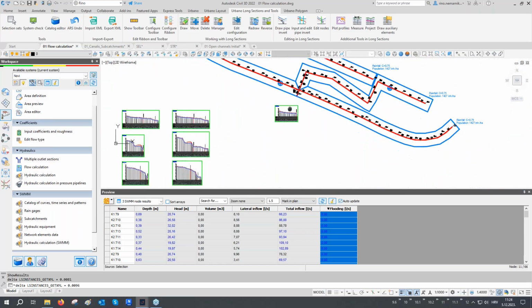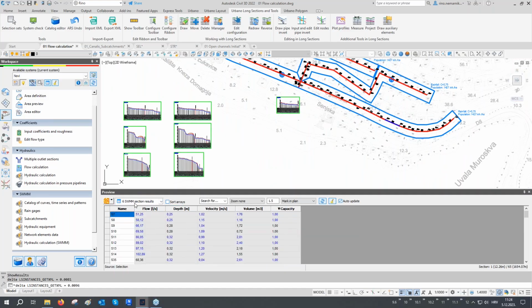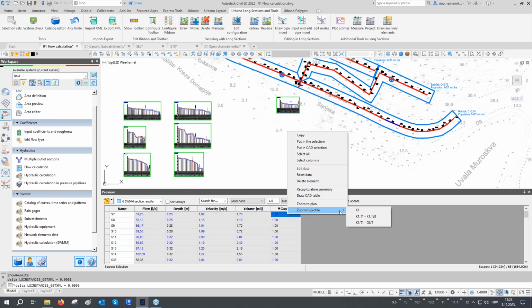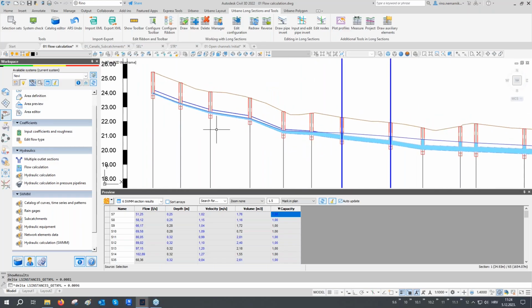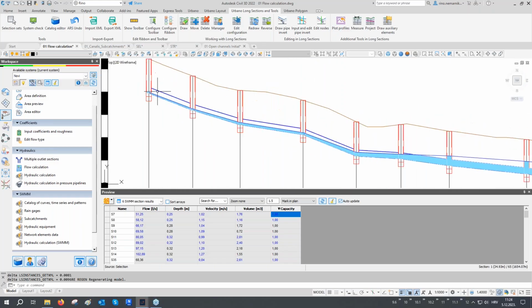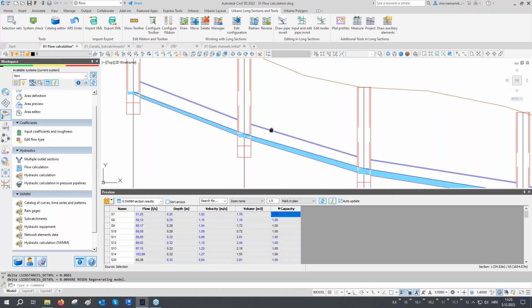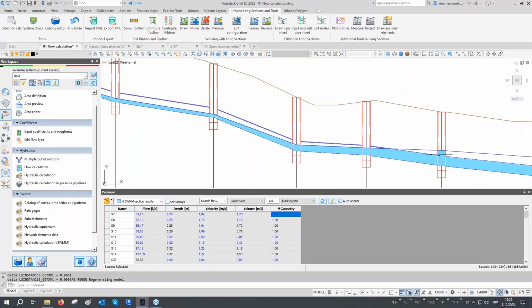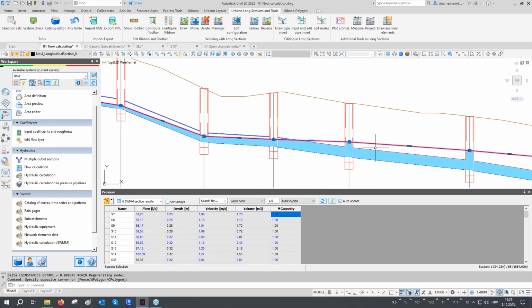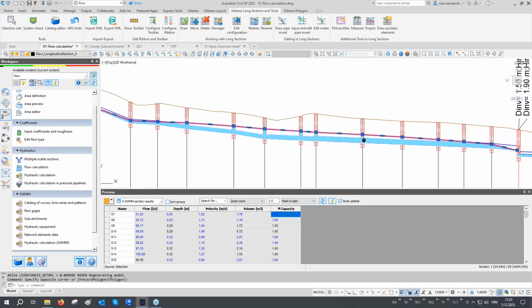Okay, let's take a look at the results at the data tables now. So if we take a look at SWMM results for the sections, again, we can see that we have some pipes that are 100% full, but now because of the dynamic wave, these water levels in pipes and manholes look different. Now the water levels in the manholes don't have to be constant. Now we have these piezometric lines that define the water levels in the pipes and in the manholes.